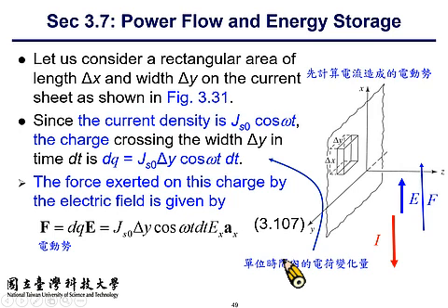So this is the amount of charge appearing in a unit time, dq over dt, because this comes from the relationship of current equals dq over dt, and this is the width times J, and this is delta y times J sub S0 over here, okay.